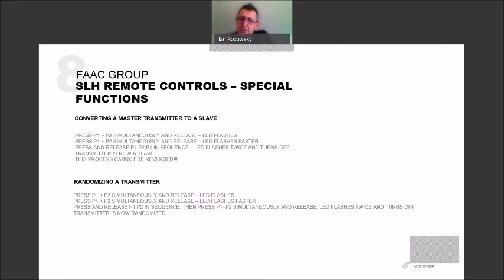The one that I didn't mention of this process of cloning is it allows you to add additional transmitters to a site without actually being on the site. As long as you have a master remote control that works on that site, you can use that master to clone a new remote control, and you don't have to be at the site to do that. You just follow that cloning process. The person then takes that new remote control to site and activates it, basically presses it twice, and it codes in and the system starts to work.